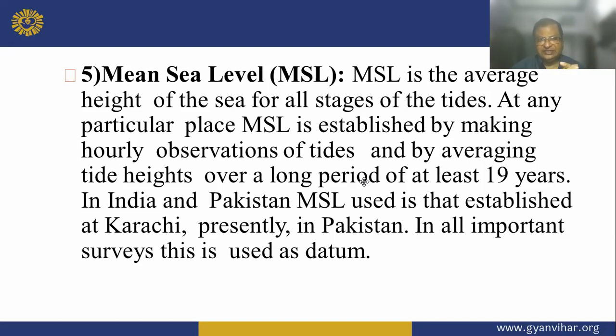MSL, mean sea level, is established by making hourly observations of the tide and by averaging the tide height over a long period, at least 19 years in India and Pakistan.